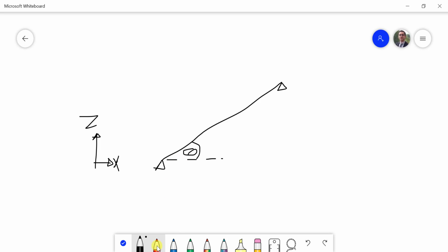So if you are applying load to this member, if you say in the global Z direction I'm applying -1, this means that the load is going to be applied on the inclined length. So if this is the uniform total that you're applying, this will be applied on the total length of your member.